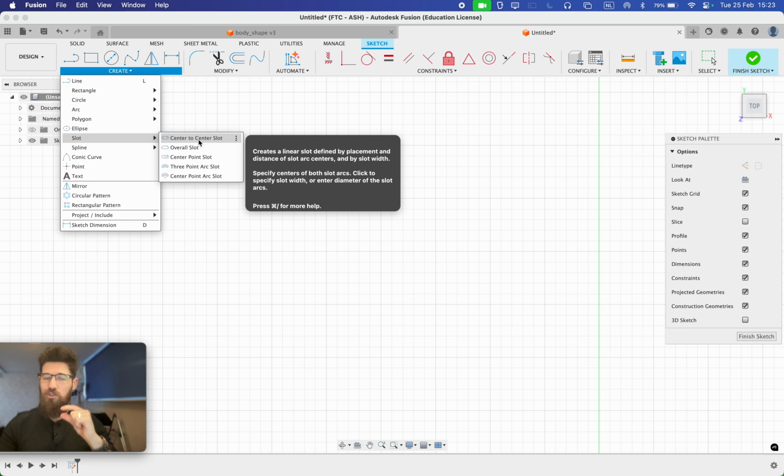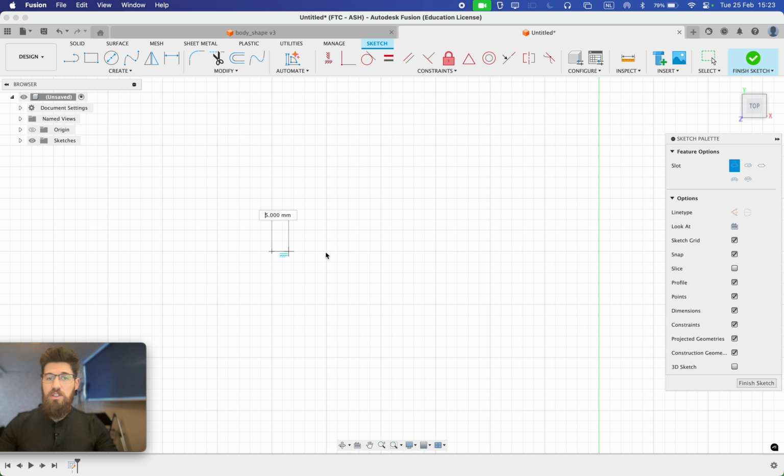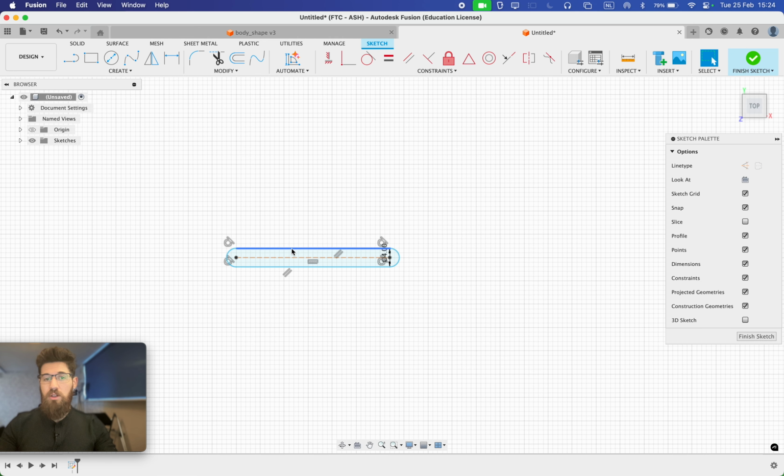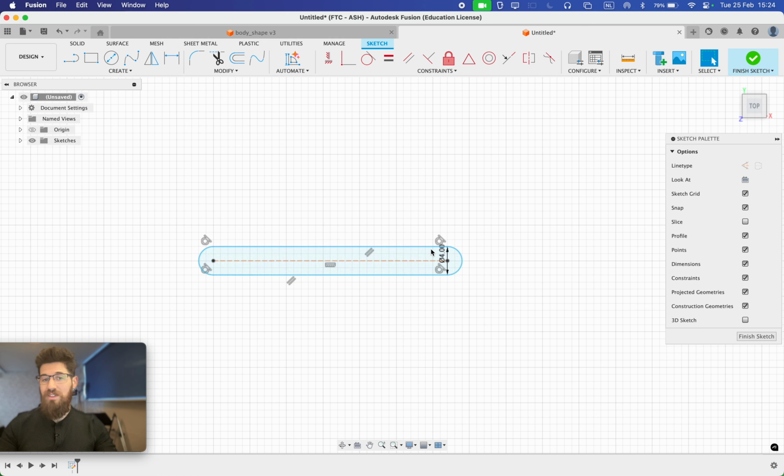If you're not exactly sure where your piece needs to fit, you may want to consider using some sort of slot. There's a center slot, we'll talk about that. So let's say I put one center over here and I say 8 times 4, because I know that my Gridfinity pattern is 8 millimeters across. That assigns my distance, and then I can say a 4 millimeter hole, and now I have a nice 4 millimeter slot that is 32 mil center to center wide. So it actually ended up being about 32 plus 4, 36 from edge to edge.